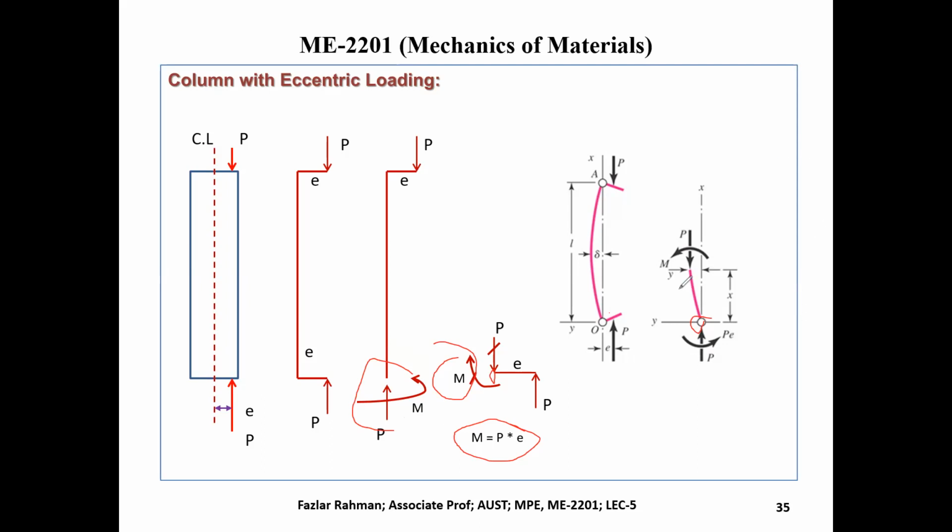Now I will cut this beam, this column, say it was like that, right? I cut it right over here. Then try to figure out how much force is working over here. And all those forces will depend on this value of X, because the Y value, the distance between over here and over here, depends on the value of X. You see at X equal to 0, delta is 0, delta meaning Y. And if X is L by 2, at the middle of the column, then Y will be maximum, that is called delta.